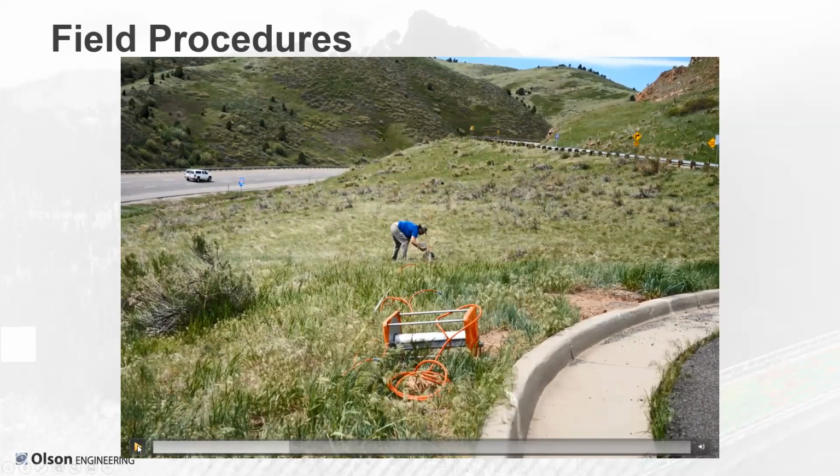Those of you that have done seismic refraction before might be surprised that we're able to do it so close to a pretty major highway. This is I-70. And the reason why we're able to do it next to I-70 is that passenger vehicles like this don't impart a lot of surface waves into the ground. Surface waves are primarily what are going to interfere with a refraction survey. So they don't impart a ton of noise.